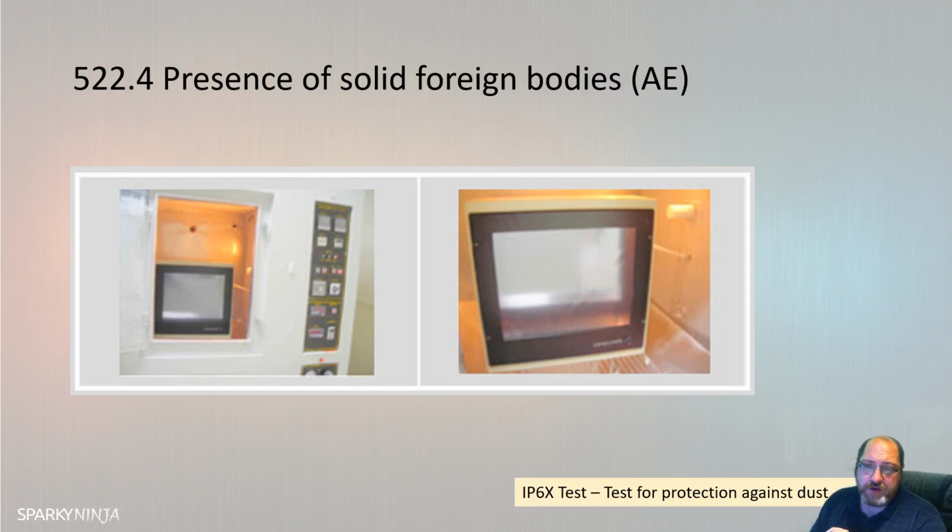flour silos or wood workshops, where there's excessive amounts of dust, or excessive amounts of debris and material in what is quite a dry environment. So the equipment may not be selected with any IP consideration at all when it should have been. So, always think about the risks of solid particles falling onto the electrical equipment when you select it and you erect it.